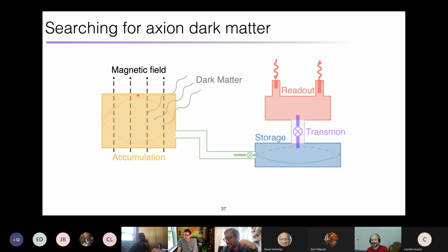But in general, they want bigger cavities ideally, and that's in some sense the reason why it gets harder to detect these as you go to higher frequencies, because the volume of the cavity gets smaller, and that actually is a net loss, right? So you wouldn't, for example, want to do this on chip. It would be great if you could, because then I could make 100 of these in a small package, multiplex the readout, and scan much faster.